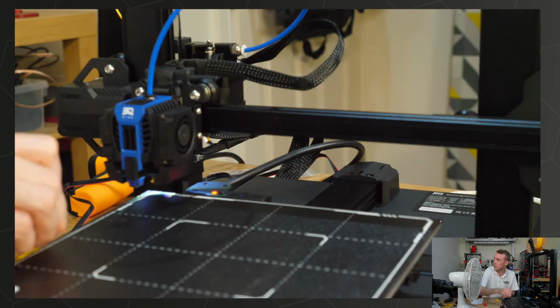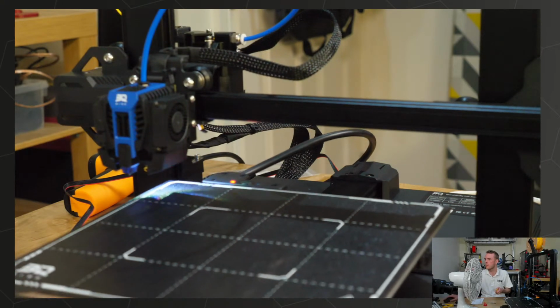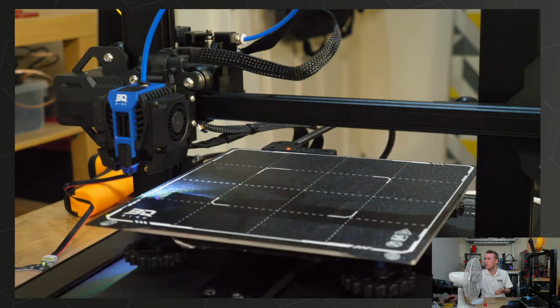Turn this off. Trouble is we start to hit bed cooling issues with the fan on. I think it's going to end up cooling the bed down. The only reason it came off is because the first layer was not really adjusted. I'm going to get a better first layer. Lots of extra cooling. Kind of want pressure advance off as well, to be honest. Or maybe it is. We'll see.